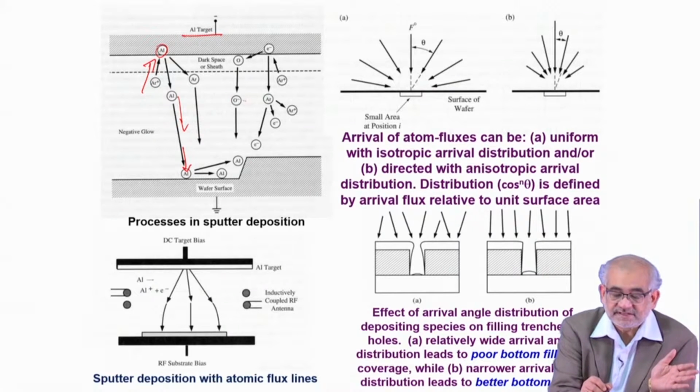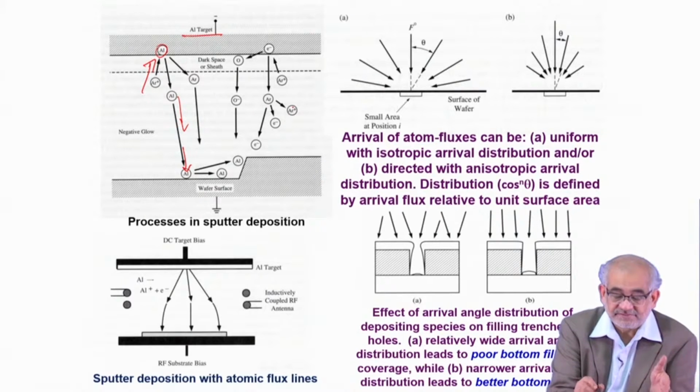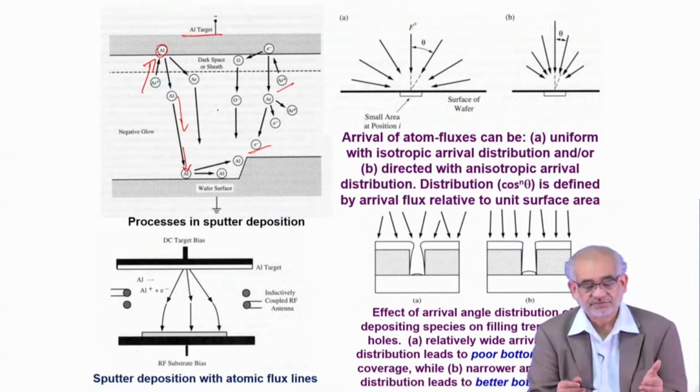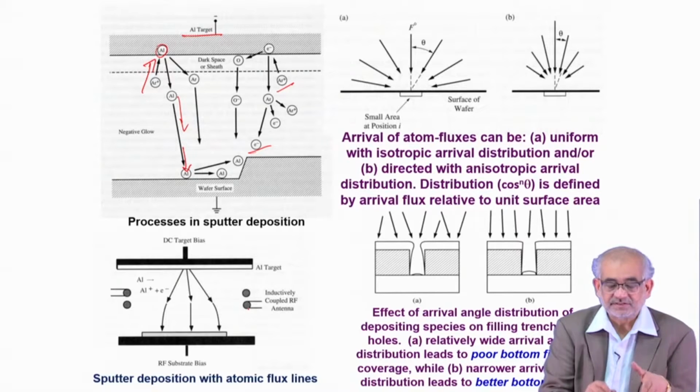But in the process, it can hit the atmosphere inside, or the atoms inside, and since we are dealing with plasma, obviously we have these argon ions, cations, and also we have electrons. So the density of them will vastly control the rate and also the uniformity and the composition with which they arrive. So this can be controlled, like I was saying.